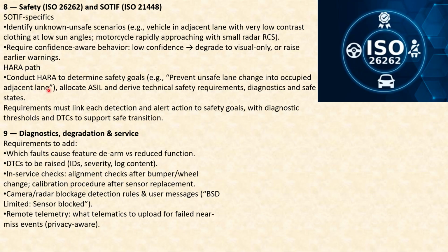Okay, so conducting the HARA is extremely important so that proper ASIL requirements and technical requirements are determined. Requirements must link each detection and early action to safety goals, with diagnostic thresholds and diagnostic trouble codes to support the safe transition.